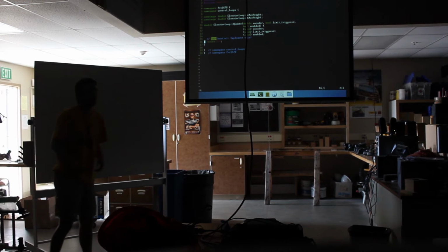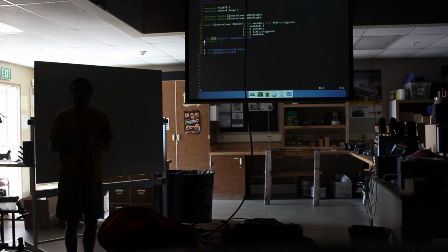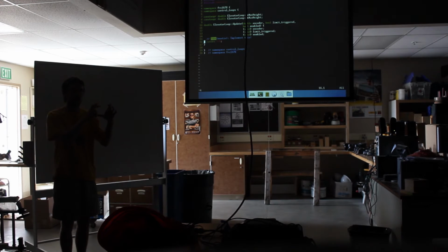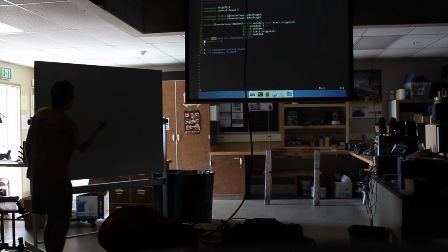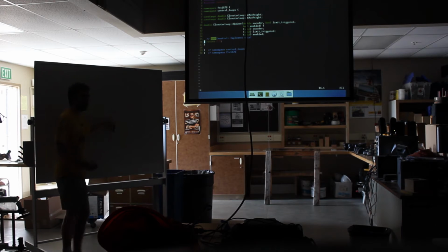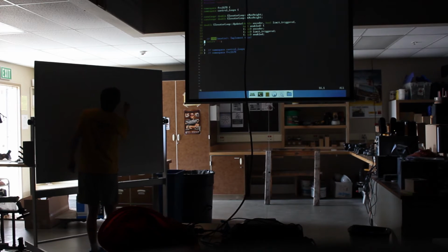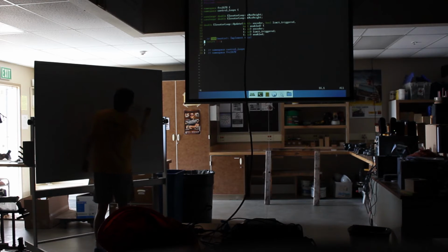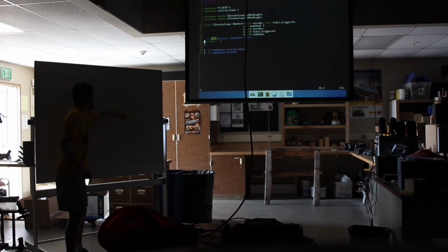So the way I like to structure the software for something like this is we're going to have a piece of the code whose job is to figure out where to go, and then a piece of the code whose job it is to go there. So you'll have, let's say, some goal coming in. This will go into our zeroing box, and this will go to a PID loop out to our hardware.